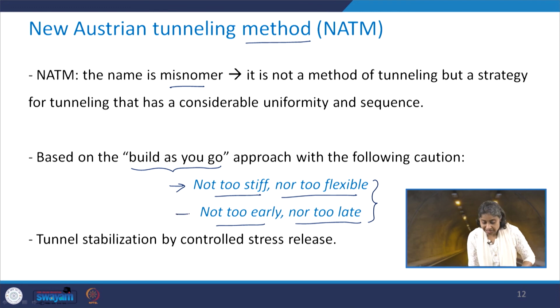Then the second line is not too early and not too late. You have excavated an opening. Now, when should we provide the support system? This is related to time. Now, we know the concept of stand-up time. This stand-up time is the time up to which the tunnel can stand on its own after the excavation without any support system.